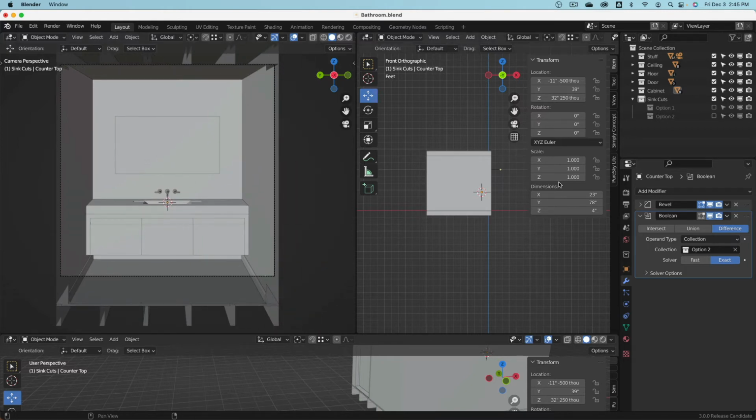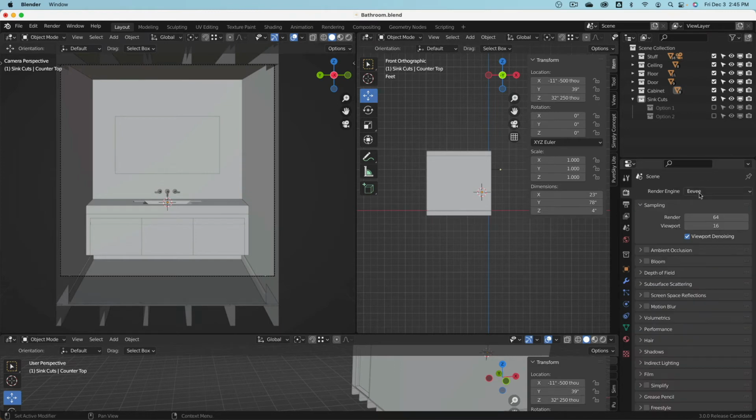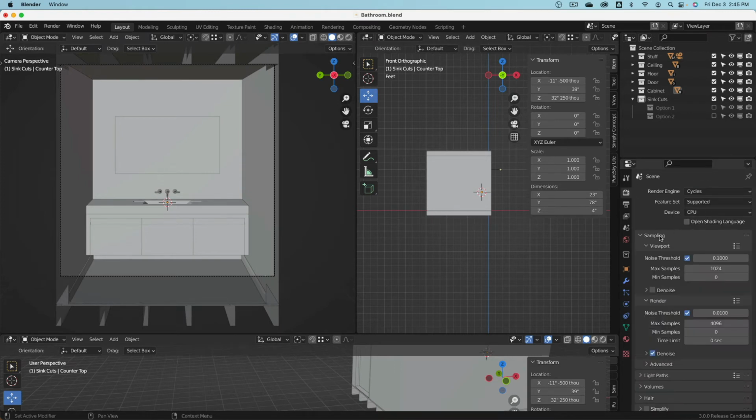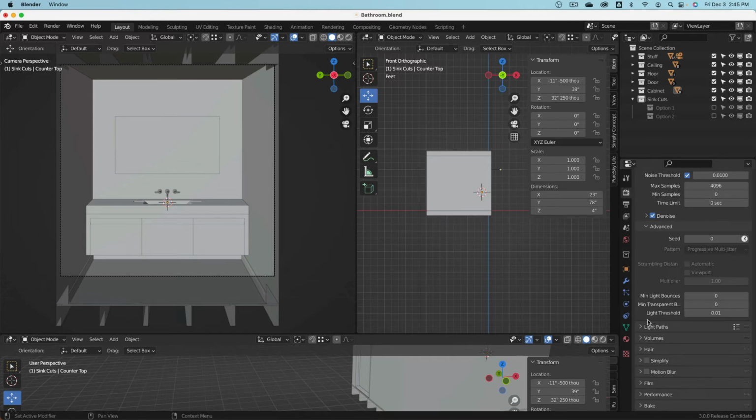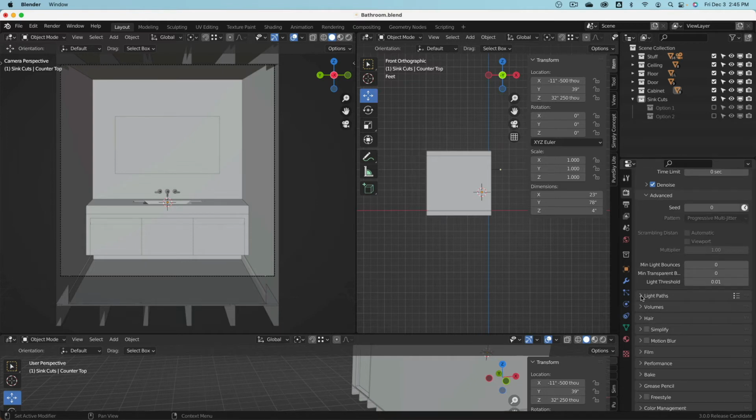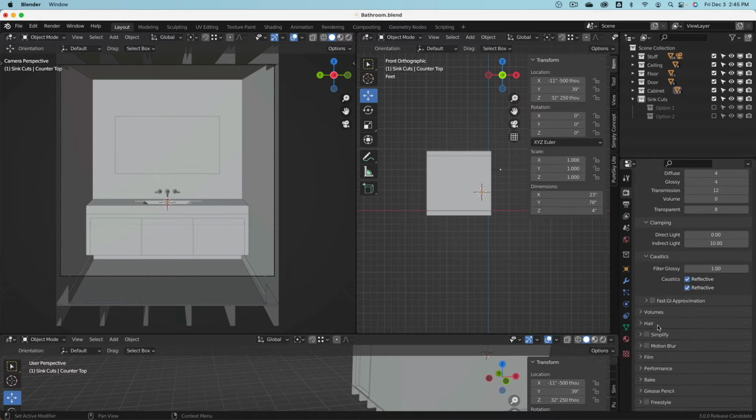So for this first, we want to go to here, set this to Cycles. Very good. Samples, we go really brutally low. Denoiser 10. Yeah, very good. So it will be really blurry renderings, but they're fast, which is good because all we want to do is get an idea of, does the light look good?